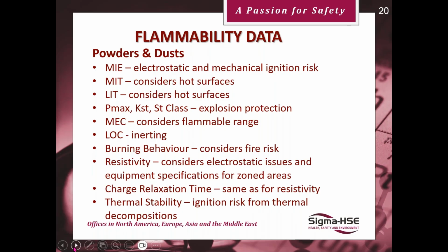Thermal stability, ignition risk from thermal decomposition. So if you're drying, whether it's a spray dryer, whether it's a fluid bed dryer, etc., you need to know how safe you are on that drying. Now, some people do things like DSC, differential scanning calorimetry, but this is not suitable.